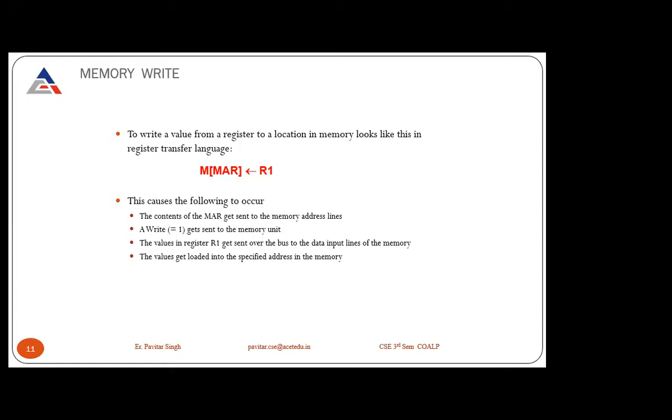That is, first of all, the address will be sent to the memory. For example, 1010 is the address. So from this address, the data value is 500. The data stored at this location is 500. After that, the write signal becomes activated and the contents, that is your 500, will be stored, will be saved.